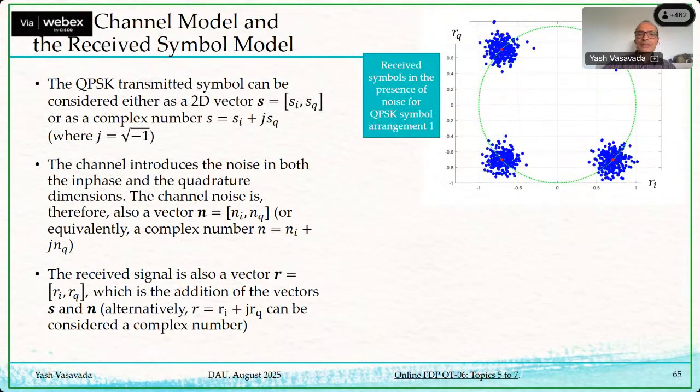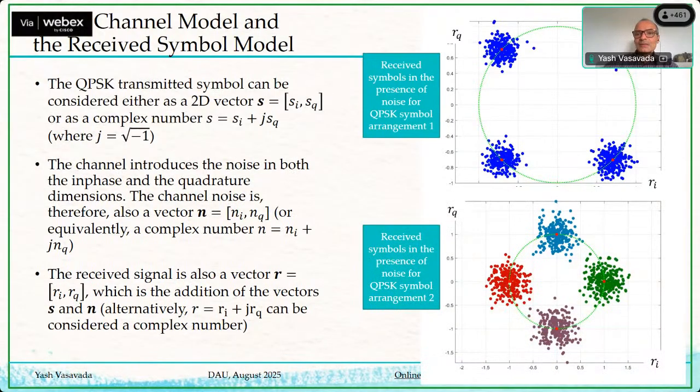Okay, so this is how the QPSK works. Yes, correct, Matthew, that is correct. Because there is no SQ component, although in reality there will be a cloud, we throw away the quadrature component of the noise entirely because it does not affect the BPSK or the on-off keying symbols. For QPSK, we cannot do that. Depending on which constellation points we transmit, there will always be some cloud around it.